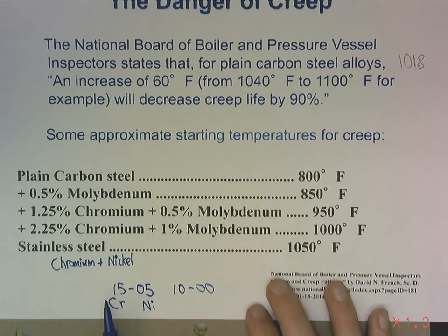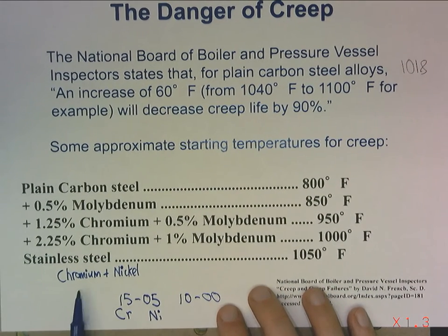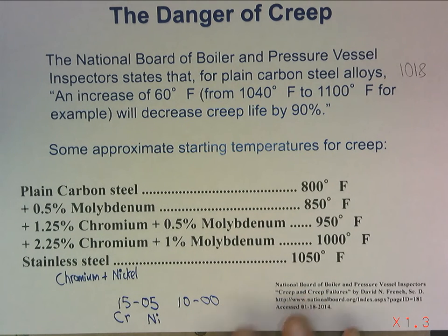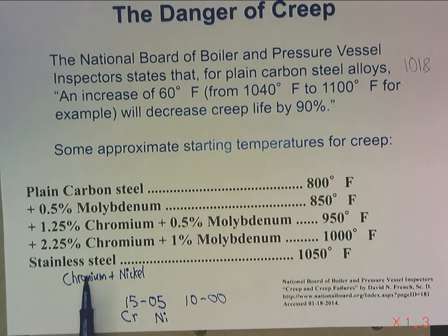Real good stainless steel needs nickel, though. Chromium just doesn't add the corrosion resistance on its own. Nickel also has a higher melting point, so it generally increases the melting point of our steel alloy.